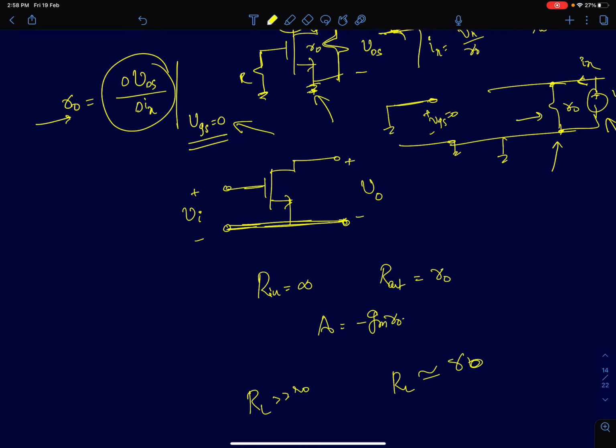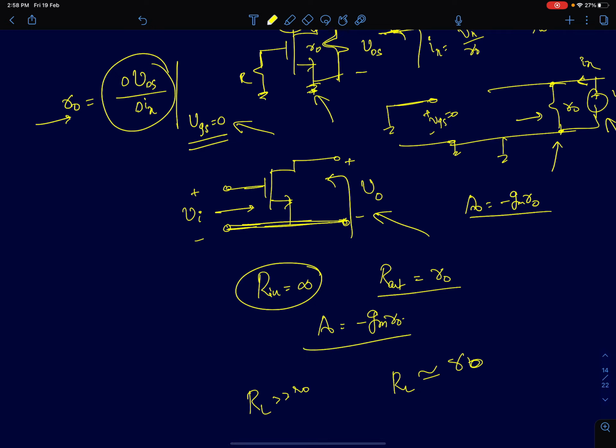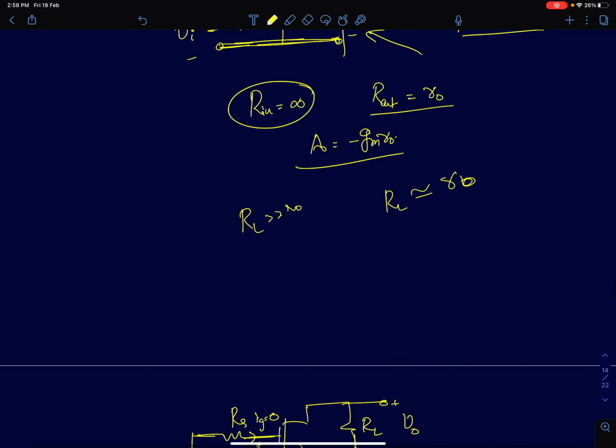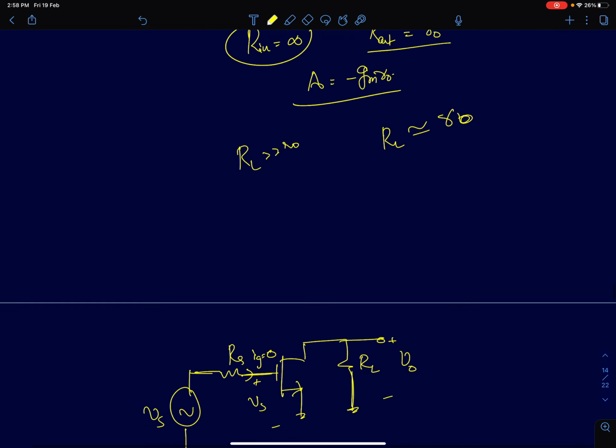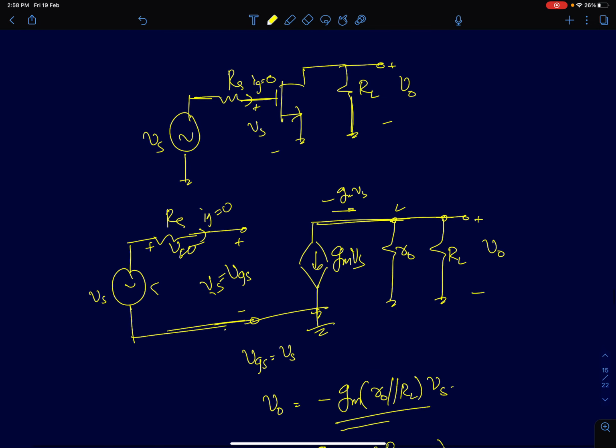So now you are looking at the common source amplifier. Intrinsic gain we just derived some time ago, which is minus gm R0. The input resistance is Rin, which is infinity. The output resistance here, you're looking into the drain, source is ground, and so it's going to be Rout. We just derived how to find the resistance looking into the drain. The intrinsic gain is minus gm R0. Now one can intuitively see this way. I'll probably analyze one circuit and then come back to the intuitions.